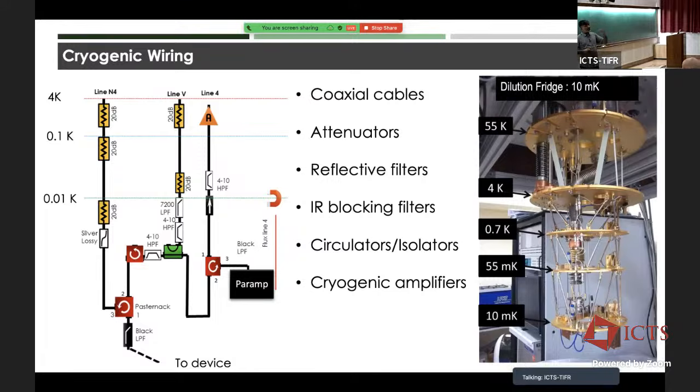So the qubit is somewhere over here, which is called the device. The signal comes down here, and then the measurement signal is routed back through this amplifier, and it again amplifies in reflection. So the scattered wave is actually an amplified copy, and then it goes up here, gets further amplified, and then there is more processing here till it goes to the demodulation circuit at the outset.